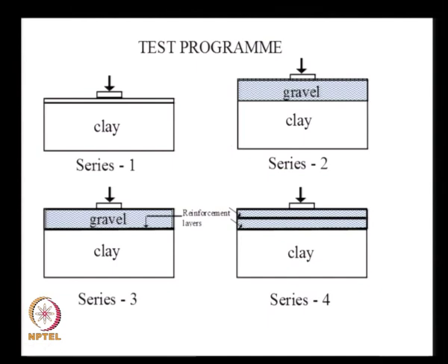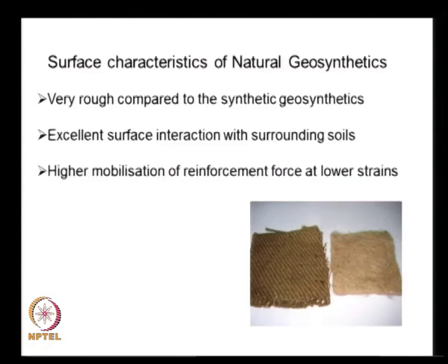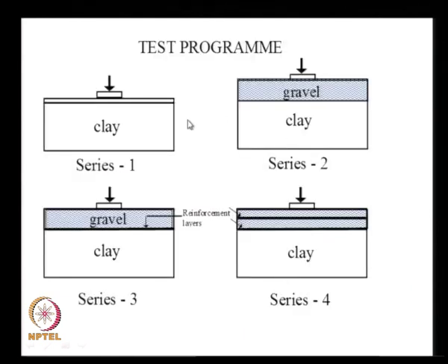Here at IIT Madras some students have done tests on the use of coir geotextile, similar to the one that you have here, for reinforcing a soft clay, and 4 series of tests were performed. The first series was the plate load test on clay soil alone, and the second series was the clay soil with some muram soil layer. The third series is the plate load test with clay plus gravel and with one basal reinforcement layer at the base of the gravel. In the fourth series there are 2 layers of reinforcement, one at the base of the gravel and another at mid height of the muram soil. Let us see how they perform.